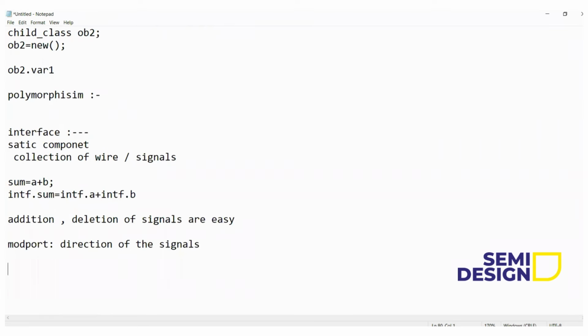Next one is my clocking block. The clocking block we also declare inside the interface. One is the clocking block, another is the program block. So why are we doing these things? Remember, in Verilog, we have a race-around condition between our DUT and test bench.